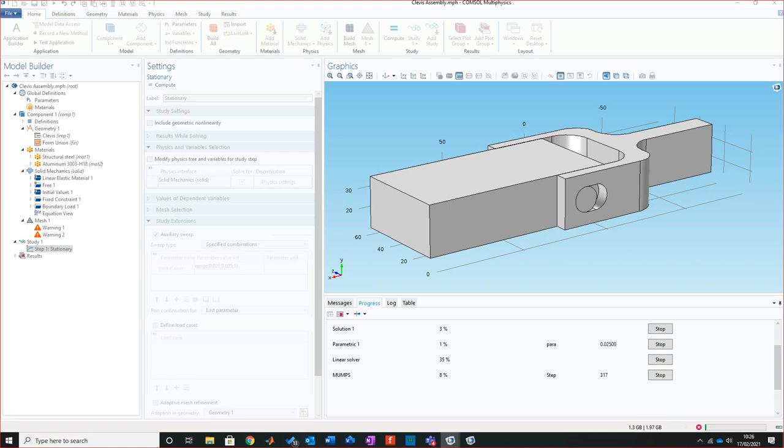What I really do want to do is I want to look at that pin, because it is the pin. This is what I'm alluding to. It's the pin that causes the big problems. When we actually ran the meshing then, it did return with a warning around that pin. We're probably not going to be able to eradicate all the warnings completely, because what it's trying to say is these areas could do with further refinement.